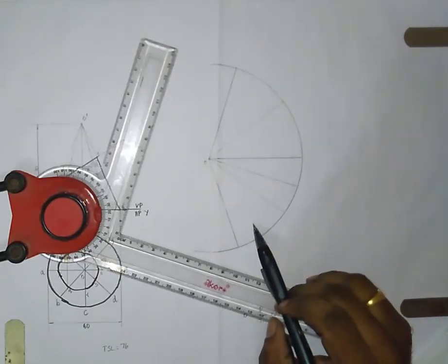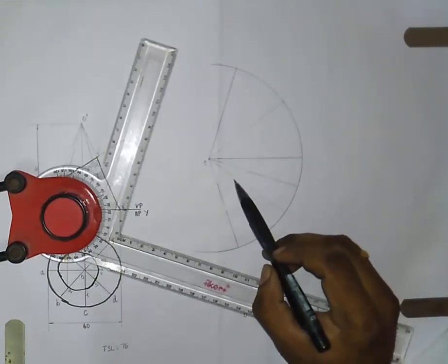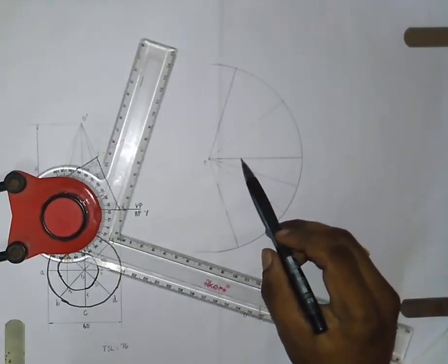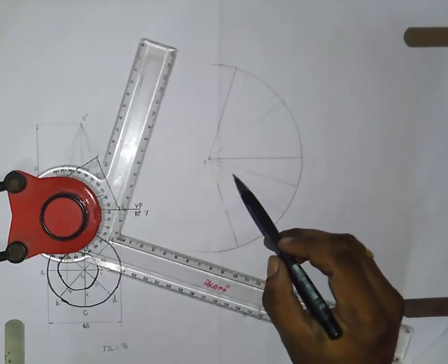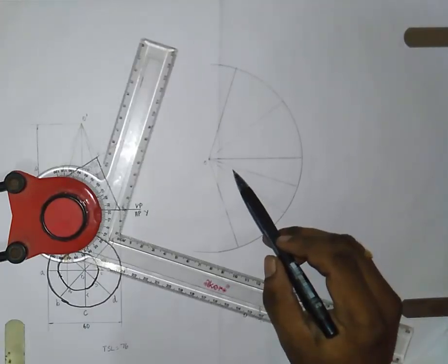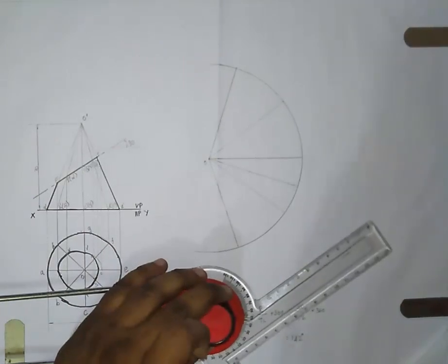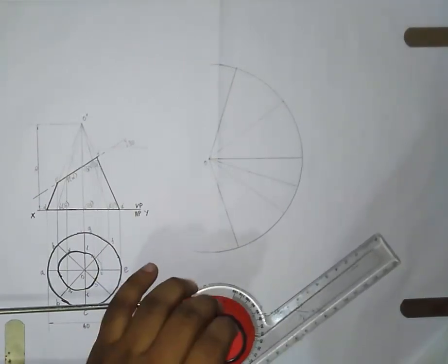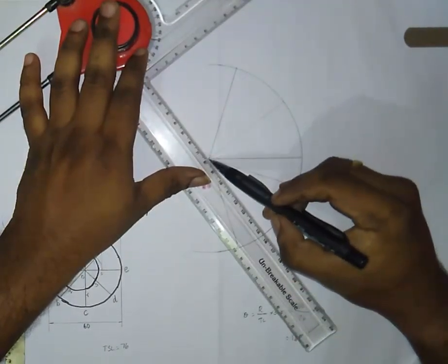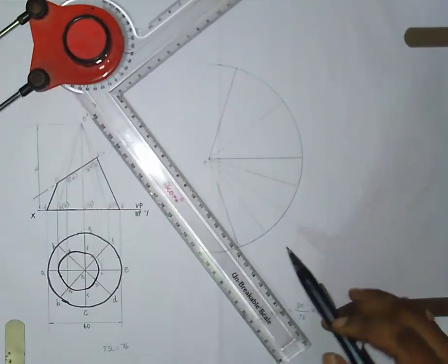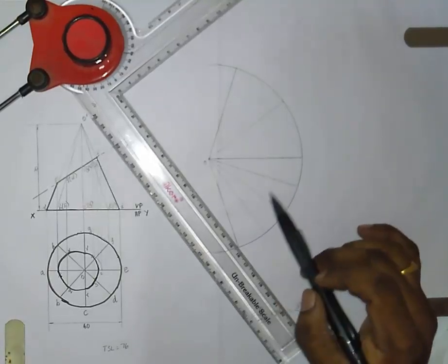Similarly, this segment has to be divided into 2 equal parts. Now this is your 35 degree, this is your 35 degree. So if I make a line here, this is your 17 degree and this is your 35. So 35 plus 17, it is 52. Just set the angle of 52 in your drafter and draw a line here. You will get exactly the division like this. Now this is 17, 16, 17, 16, cumulative 71.